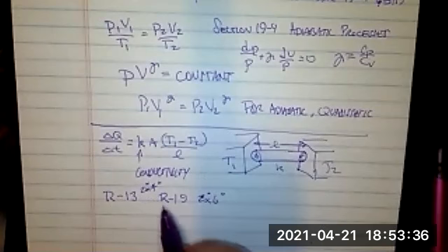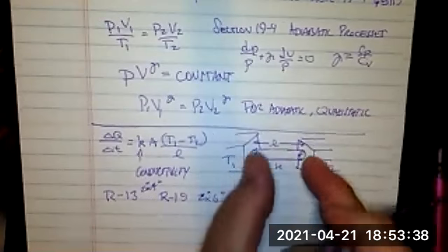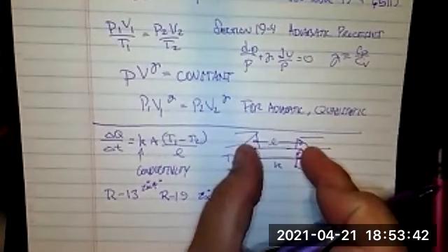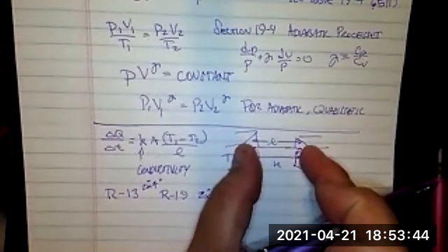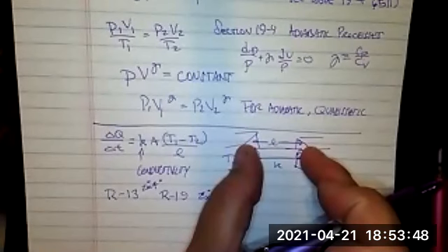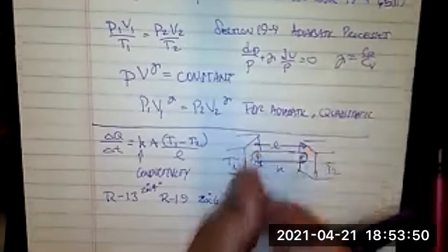Because the reason R19 is good is because of this L being so thick. And this L being so thick is partly due to air trapped in it. And air is really the good insulator there, better so than the fiberglass that the insulation is made out of.